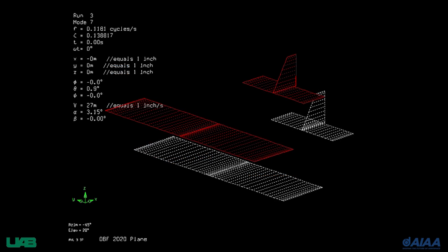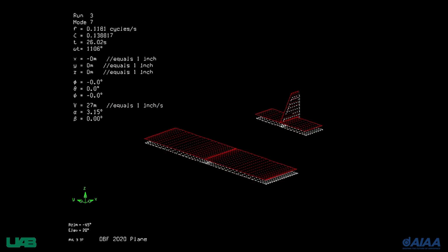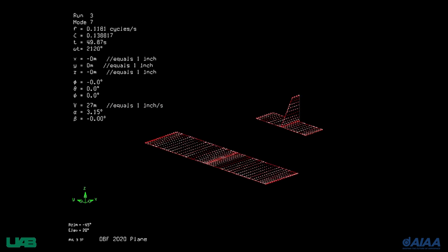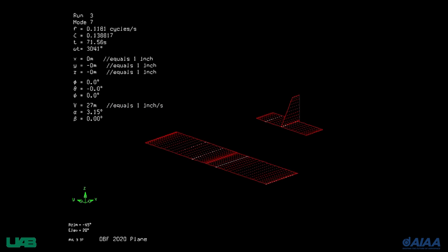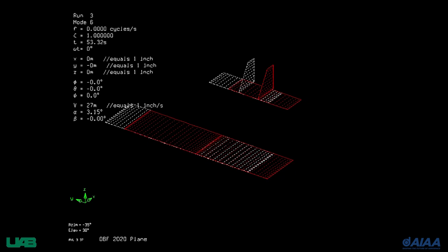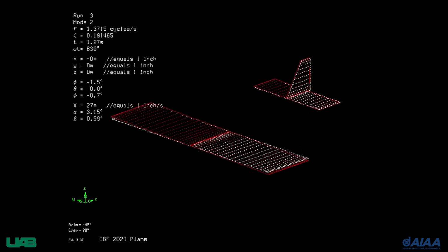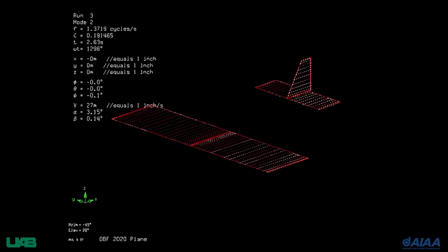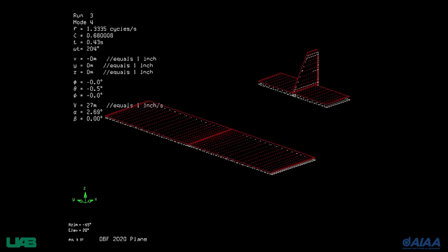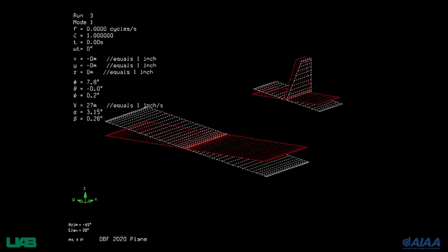MATLAB was used to optimize the horizontal and vertical tail volume coefficients based on the horizontal coefficient range of 0.5 to 0.7 and a vertical coefficient range of 0.04 to 0.07. Lever arm distance was calculated for every possible vertical and horizontal volume coefficient combination until only 5 of reasonable length were optimized and narrowed down. The final horizontal and vertical tail volume coefficients were 0.52 and 0.04 respectively. The static and dynamic stability derivatives were in a variable range according to the military specification stability document.